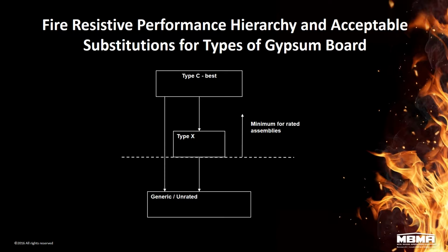Type C is the best board, the best performing board, and one could substitute Type C board for a Type X application, but not the other way around. And we have seen that in some situations where incorrectly Type X board has been used where Type C has been required, and that just doesn't work and is a rejectable issue.